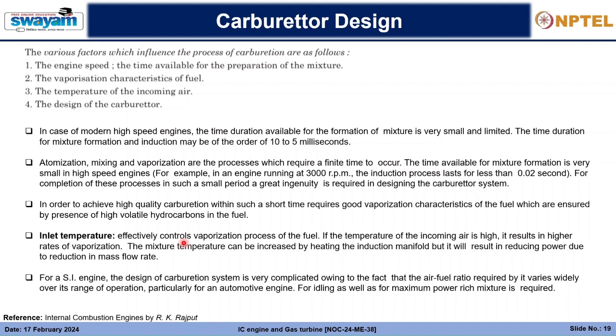I will also explain the theory behind the carburetor design, how the mass flow rates of fuel and of air are calculated, and we will get the net mass flow rate and air fuel ratio. Then we will solve a few problems on carburetors, and finally we will see how in modern systems, instead of carburetors, petrol is directly injected in the intake manifold, and how those systems work. That will complete our carburetors, and we will continue this in the next session.